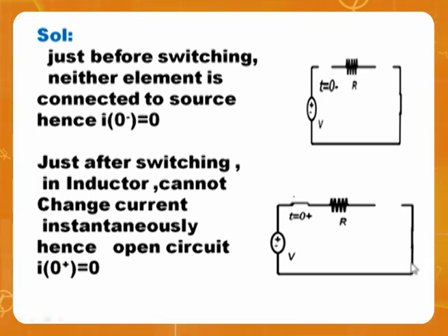Similarly, now the switch is closed, as you observe here. The switch which was open is closed. But what happens to the inductor? It cannot change. The inductor is open here, therefore it remains open. The capacitor is short, and remains short. But still one open circuit is sufficient, therefore the total current is 0. So this is an argument to talk about series circuits.